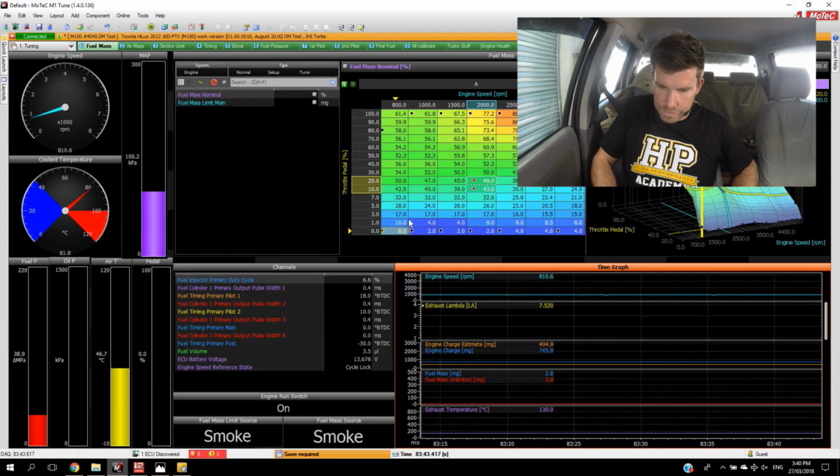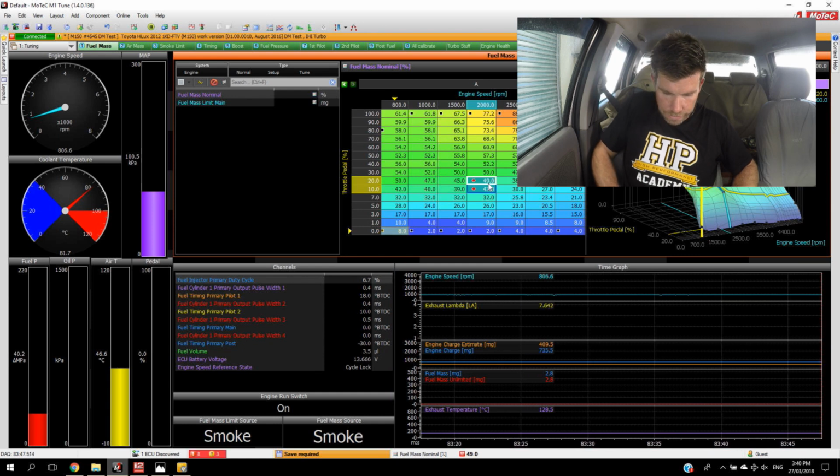So this again comes back to the graph that we've just looked at. A longer pulse width means that our combustion process is going to be happening later in the engine cycle, and this increases our exhaust gas temperature. So let's just jump across to our tuning software again, and I'll just get us back to where we were there.